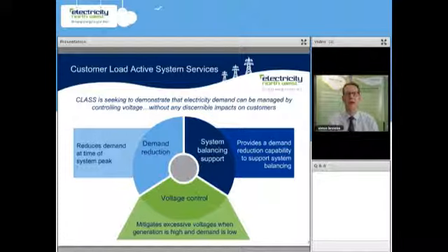So there are some quite extensive trials to actually work out, when we reduce the voltage at any particular time of the day, what relationship do we have? So what does the demand move by? The reason why we want to know that is because we want to be able to change the voltage at the time of system peak to defer the need for reinforcement, effectively buying ourselves a window of opportunity.